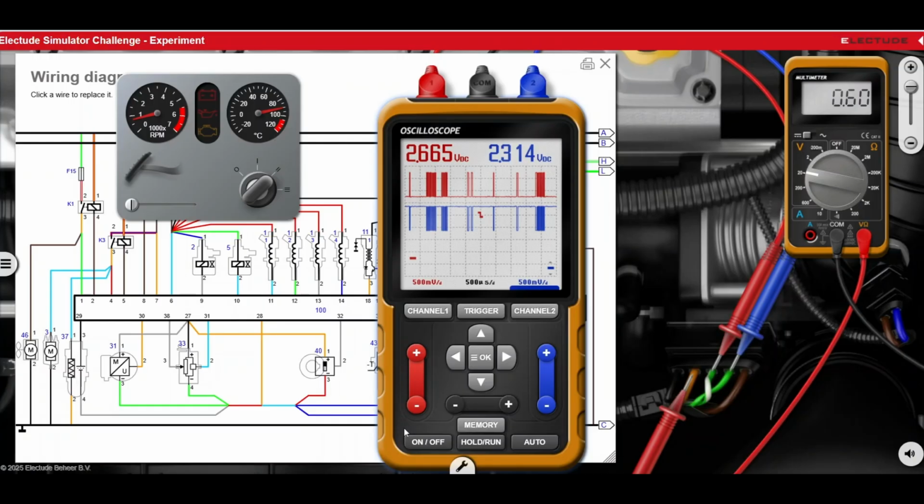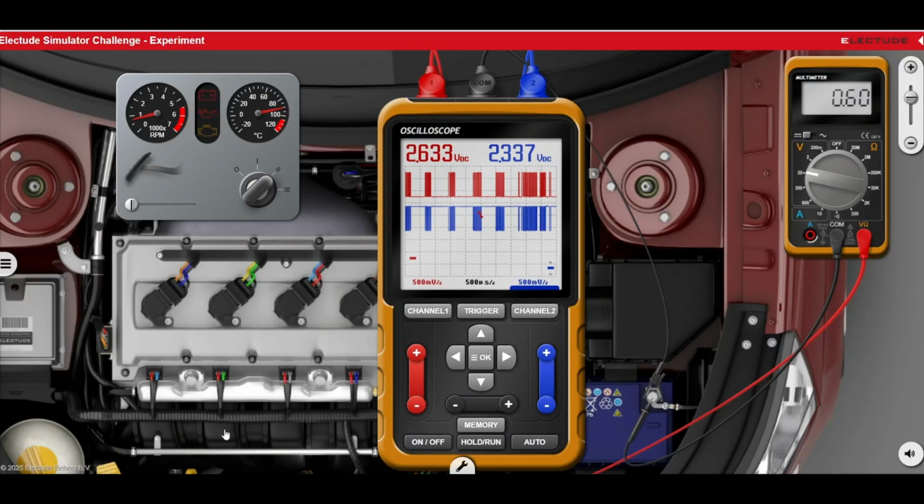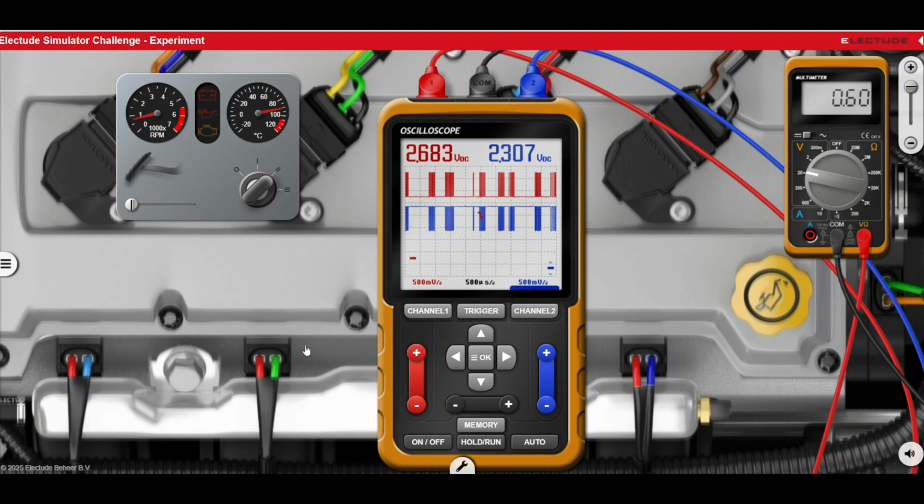So let's get rid of the wiring schematic. With experience, sometimes you don't need the schematic for everything. These are injectors, so obviously one of them, especially if you look at the wiring, the red wire is common to all injectors. If you know anything about how injectors work, or if you look at the schematic, again, let me bring it out just for emphasis.